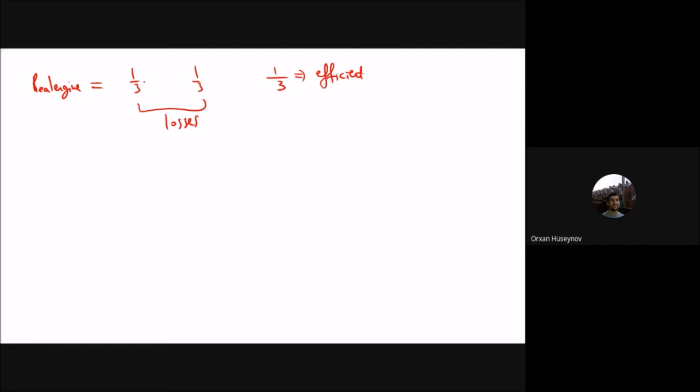Why do we divide into 2/3 and 1/3? One part is due to friction. You have frictional losses because of the bearings and the rotating equipment inside the engine. Therefore, you have this type of losses. The next part of the losses is due to heat loss, because you are burning fuel, and that fuel has combustion energy, which is lost as heat. So you have 2 losses.